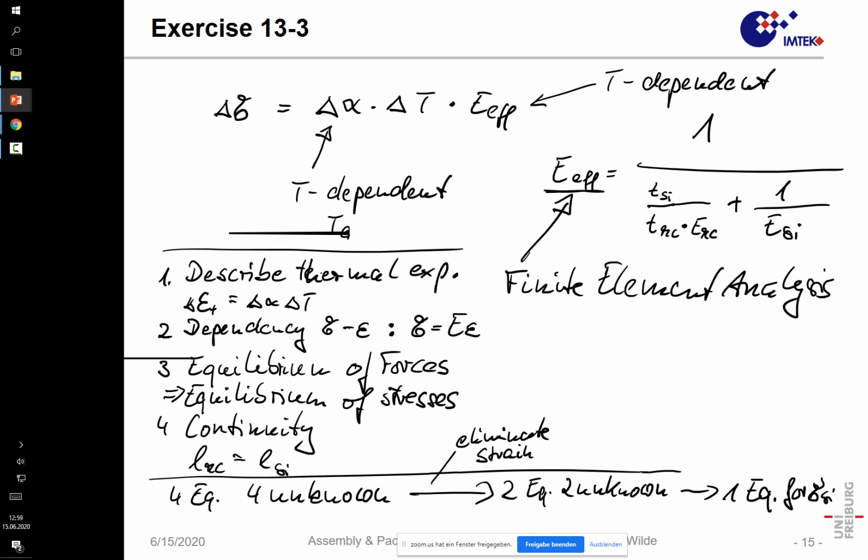Again, please note, thermal expansion alone, for instance, in a homogeneous body, will not lead to elastic strain, and it will also not lead to elastic stresses. But there will be stresses and elastic strains, for instance, if we have a homogeneous body which has a temperature distribution.